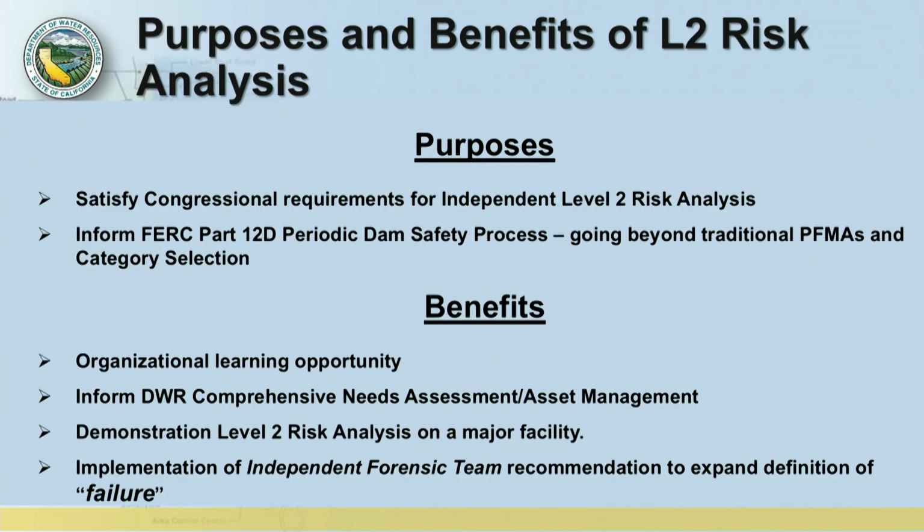Purposes and benefits of a Level 2 risk analysis. Purposes include, first of all, it satisfies the congressional requirements for an independent Level 2 risk analysis. It also informs the FERC Part 12D periodic dam safety process, going beyond traditional PFMAs and category selection. Remember, the independent consultant still has to make their report, and they have to incorporate these results in it.